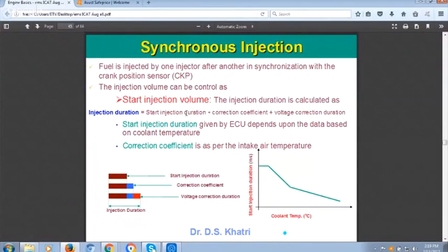Now when the starter motor is providing this, it draws very high current. From where will it draw the current? From the battery. When it draws high current from the battery, whose voltage is generally 12 volt, that voltage drops down. This is a very, very peculiar behavior. Your pump and injector flow rate characteristics are designed for 12 volt. Suppose when you provide 12 volt to an injector in a 2 millisecond duration of injection, it injects 2 milligram of fuel.